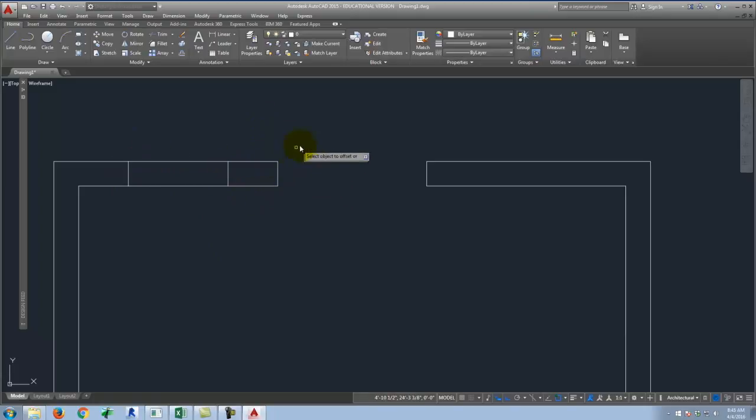Now, in convention, plans with doors have no wall below them, so we don't see any walls, so we trim out for a door. In the case of a window, we do see there's a wall below the window after we cut through it, so we end up with just 2 lines representing the window, like this.